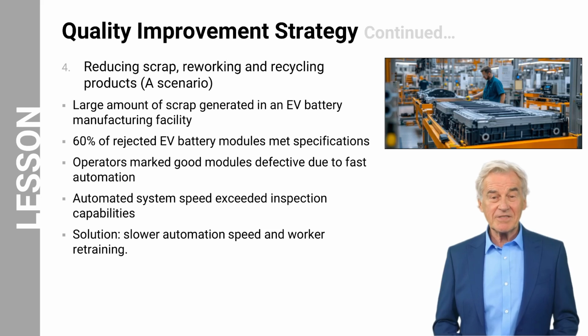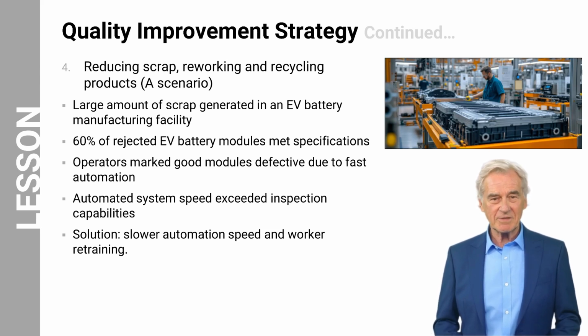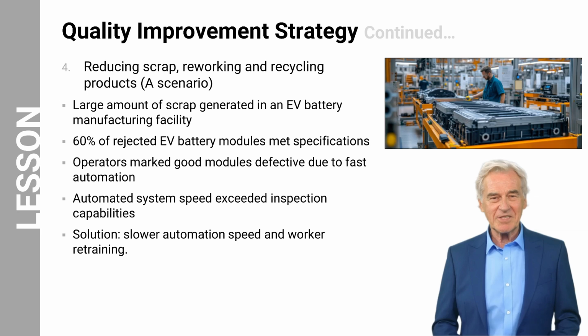When a manufacturing facility is experiencing excessive scrap, rework, and waste, it is crucial to first determine the source or cause of the majority of the problems. Having a detailed sampling plan and quality checks at critical processes can help reduce scrap, rework, and waste. An efficient sampling plan not only helps technicians detect these issues, but also determines if the process needs to be shut down to investigate the source of the problem further. However, in some instances, large amounts of scrapped, reworked, or recycled components are a symptom of another problem.